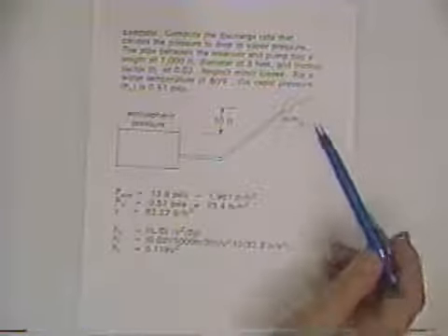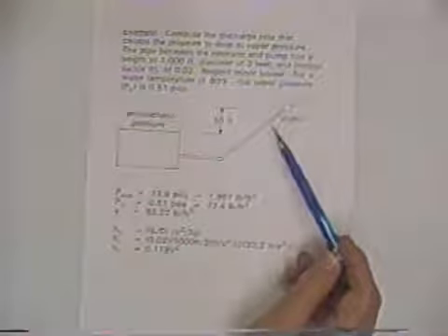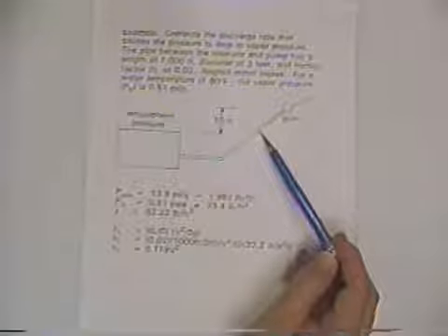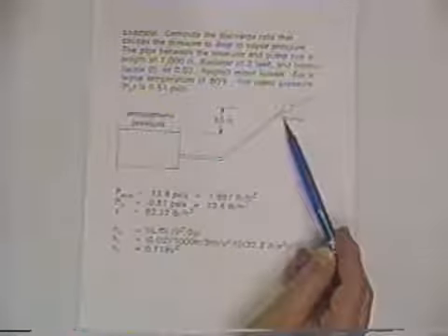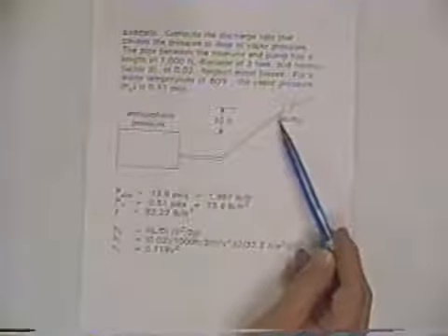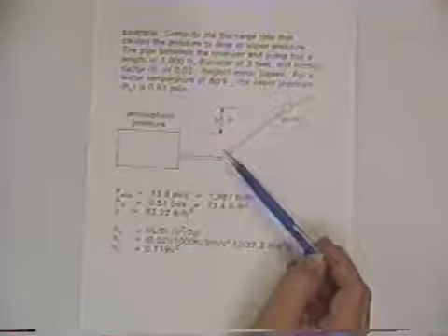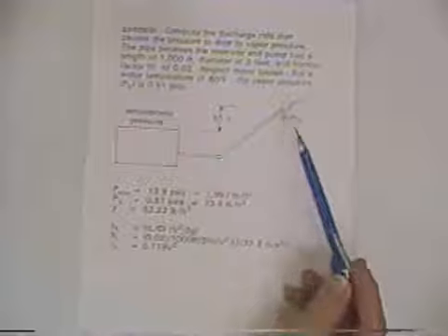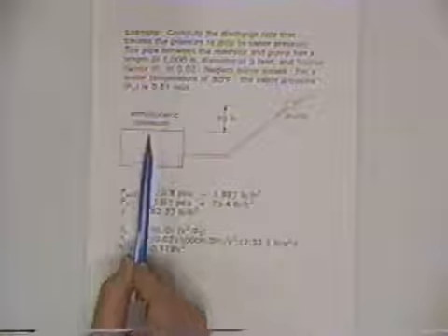And so in this problem, and these type of problems can be worded differently, we're determining a discharge rate. We fix the elevation of the pump, and we want the maximum discharge rate we can have before cavitation becomes a problem, meaning that we drop the pressure all the way to, not quite zero, but to vapor pressure. Another way of wording this type of problem is how high, for a given discharge rate, could the pump be above the water surface in the sump?